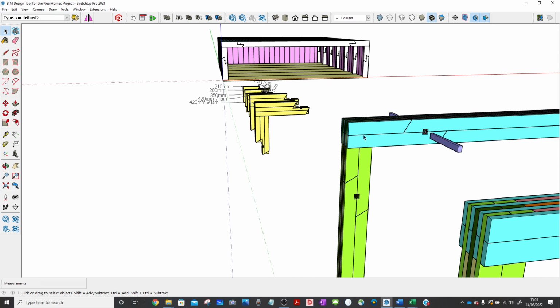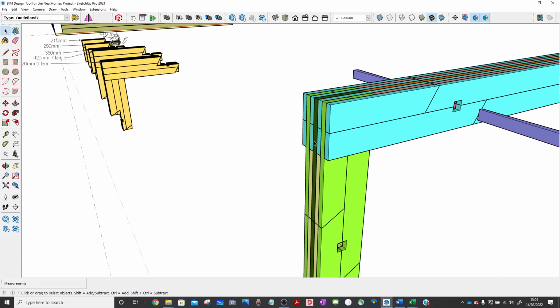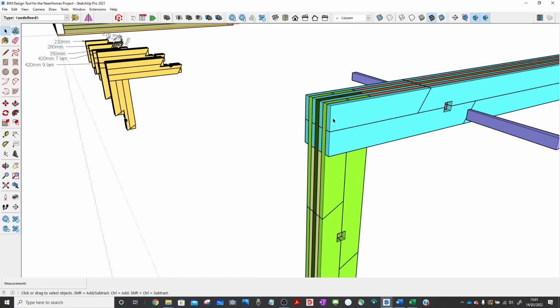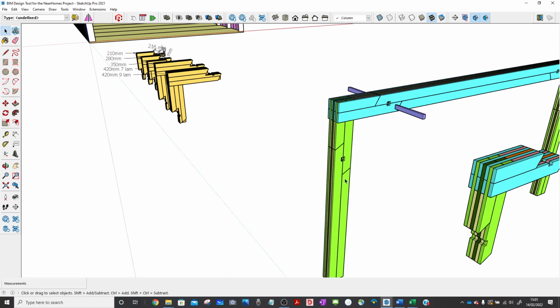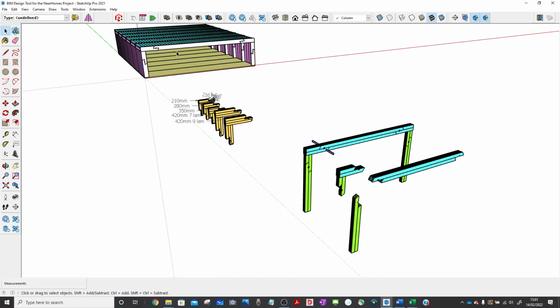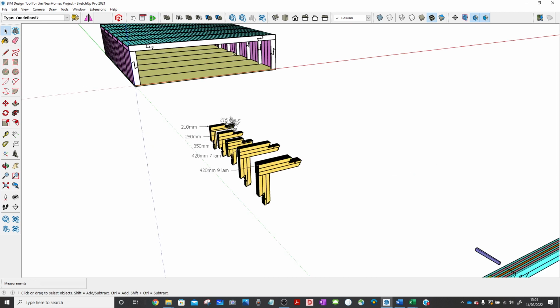It was actually the stiffness of the glued area here. That was the bottleneck. So all we had to design for this, and even the bending in that span, the bottleneck was always going to be the rotational stiffness or the moment resistance within this.